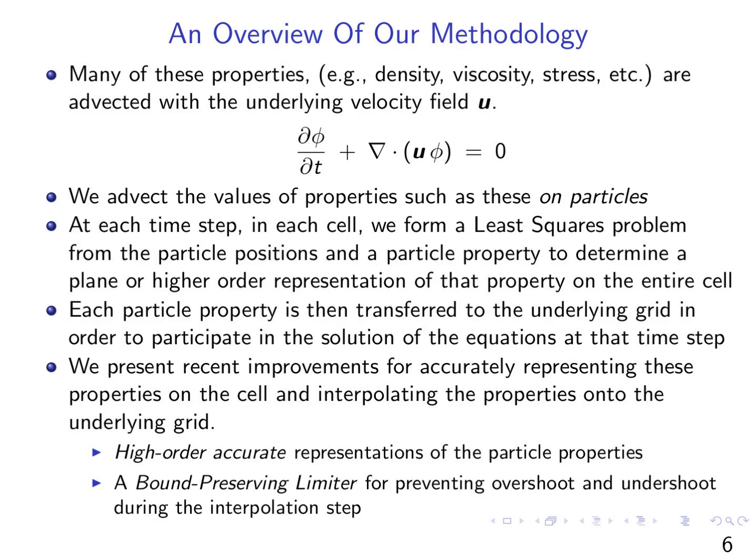So let's take a look at our methodology. Many of the particle properties such as density, viscosity, stress, characteristic functions, they're advected with the velocity field using the equation here from the previous page. And what we do with this is that at every time step, we're going to form a least squares problem, creating a plane using the particle positions and the particle property values.